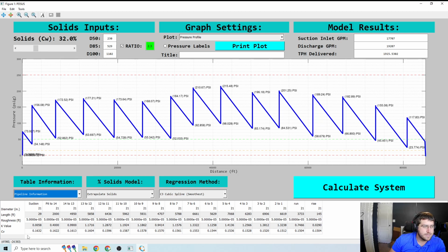This gap between the two might be larger because the effect of the sealing water opposed to the total flow is much larger. That's a problem. In a lot of processes, your percent solids are not uniform. For example, a pumping system that's pulling out of a mining pit. So you have a very inconsistent value of percent solids coming in. So to assume that your percent solids here are a value to give you a percent solids there might give you very misleading results in the middle of this thing, right?